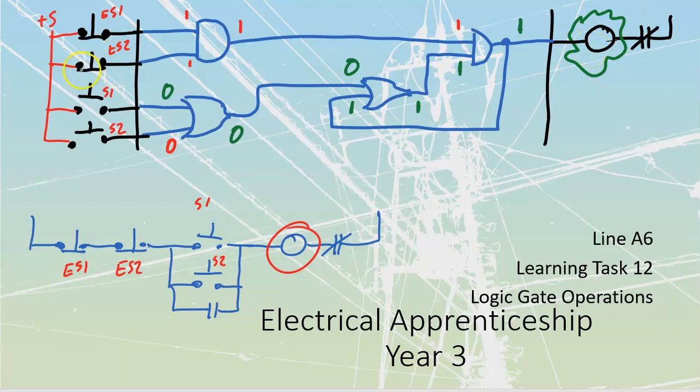What we then do is we can go and hit this stop, any one of these stops. I don't care which one, we're going to hit this bottom one over here. If I hit that stop, it's going to open it up, which means that this is going to become low over there. As soon as I get a 1 and a 0, this becomes 0. That becomes low. As soon as I get that, that becomes a 0. That carries over to there, which means that this AND gate is going to go and become 0. It's going to shut off.